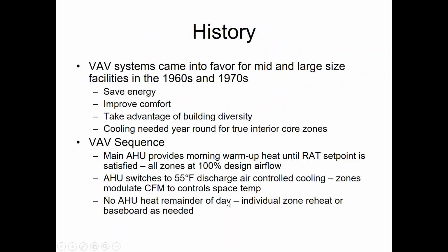All right, so before we talk about VVT, we got to refresh a little bit on VAV just so you understand why VVT was even born. So VAV systems have been around for 50 years at this point. Very well-established type systems. They've done a very good job in mid and large size buildings, especially in office buildings. Main purposes for having a VAV system: get individual zone control for individual occupants. That's a primary driver. Save energy by slowing down a VFD.